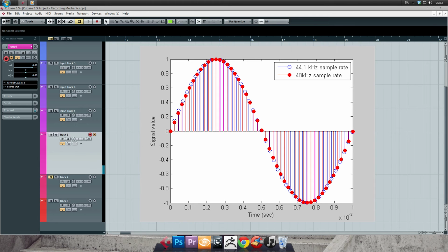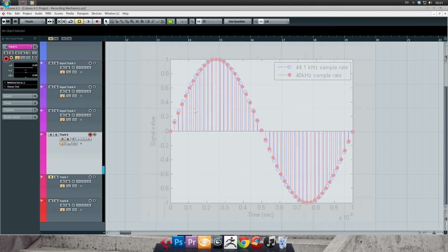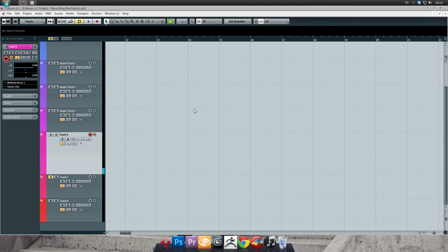And all this goes on in your analog to digital converter, which is probably placed inside your audio interface, unless you use an external AD/DA converter in sync with your interface. But if you're not sitting in a $1 million studio, your converter is probably placed within your audio interface. And on most audio interfaces, you can switch between different sample rates such as 44.1, 48, 88.2, and 96. And sometimes you can even go for 192, which I wouldn't recommend.